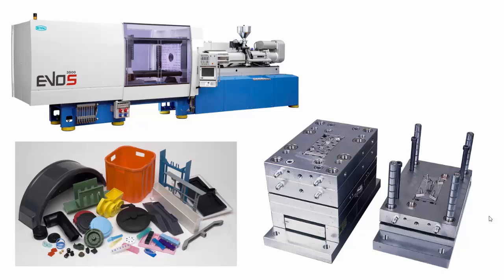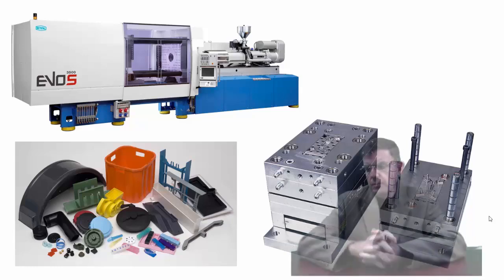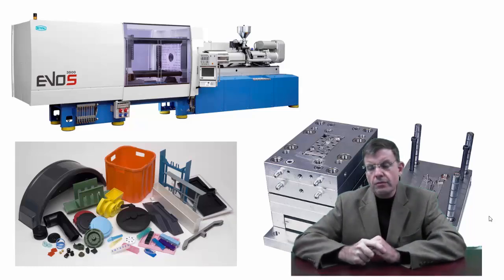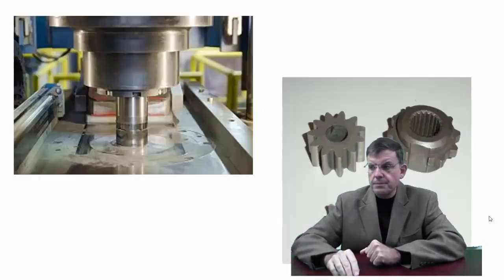Okay, so it takes quite a bit of effort, in fact, to machine these molds, but if they're made out of a sufficiently strong steel, they can be good for hundreds of thousands of parts. And there on the bottom left, you would see an assortment of typical injection molded parts. So a very traditional, very well developed, very standardized, and well known process.